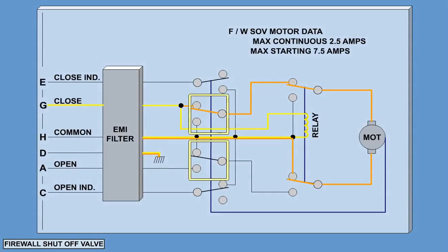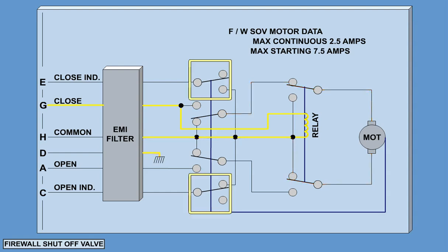The 2 motor control microswitches are actuated by cams as the valve ball rotates and are used to limit the motor rotation. When the valve reaches the end of its travel, one of the switches opens to interrupt current to the motor. The 2 position indicator microswitches are actuated by cams as the valve ball rotates through its 90 degrees. They are used to indicate valve position to the data acquisition unit.